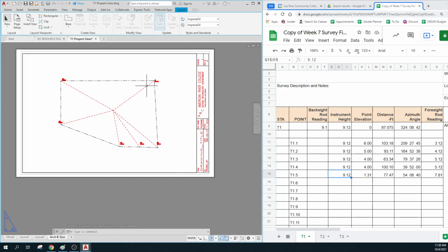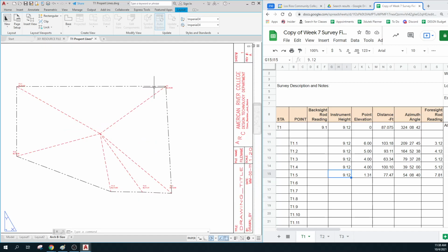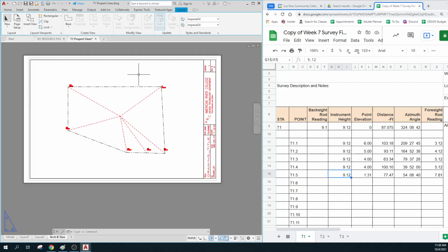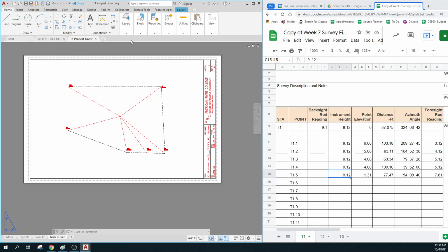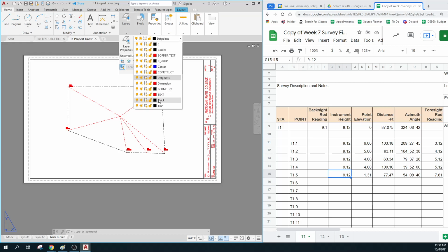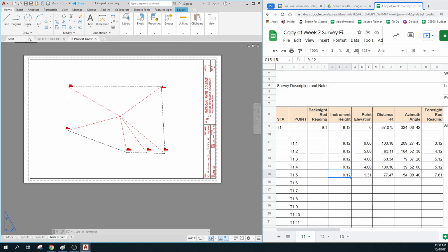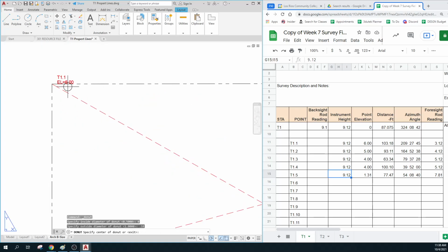And then I have to just go back and do all of my cool stuff that I'm supposed to do. Right? So I'll put in my donuts. I'll put myself onto probably my text or my thin layer. I'll put them on my thin layer and I'll put a donut at each one of those. My inside diameter is 0. My outside is, let's say, 0.18 maybe will be a good one. Let's just see. That looks like a good size.